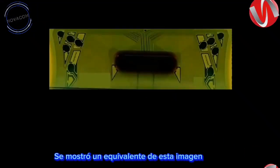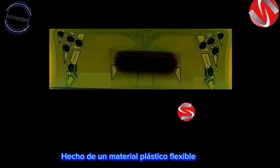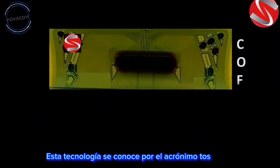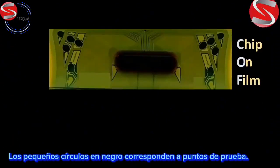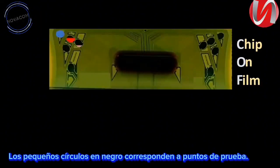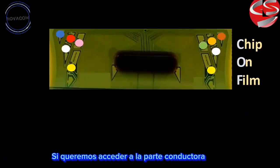Hello. In the previous video, an equivalent of this image was shown. It was a chip engraved on a film made of a flexible plastic material with conductive tracks. This technology is known by the acronym COF, which is an abbreviation of chip on film. The small circles in black correspond to test points. They are not directly accessible because they are covered with an insulating material which must be removed if we want to access the conductive part.